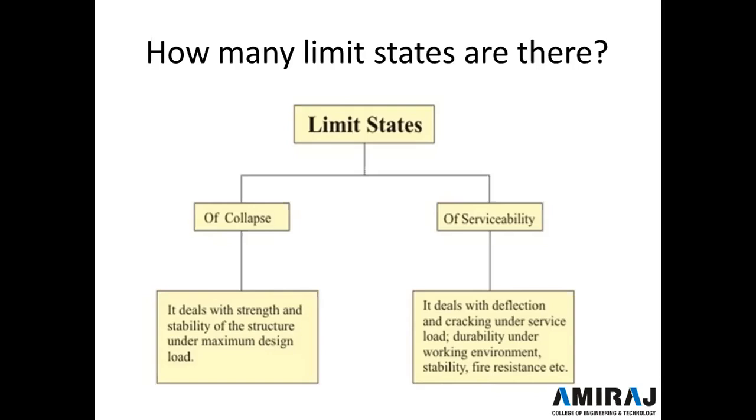These limit states deal with discomfort to occupancy or malfunctions caused by excessive deformations, vibrations or corrosion, etc., right? So these are the two types of limit state: limit state of collapse and limit state of serviceability.